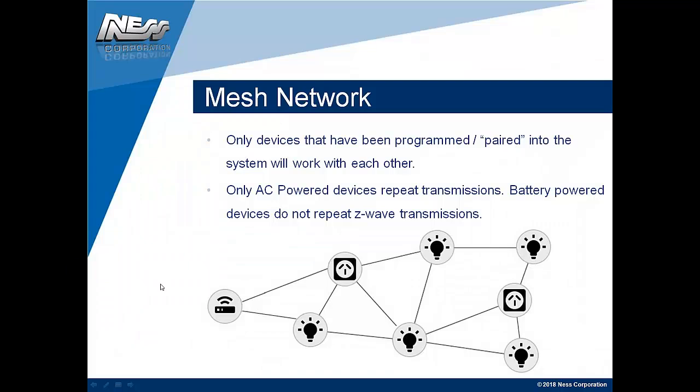So it's a good practice, not mandatory, but it's a good practice when you're learning a device in, that if we're learning this device light switch in here, then to put it in the location where it's going to be installed in relation to the other gateway, so it can build its mesh and know what partners are around on the way to the gateway back there. If you programmed it all in one office and then put it out in the field, it's got to rebuild the mesh live on the network, so it's best to do it while it's learning in.